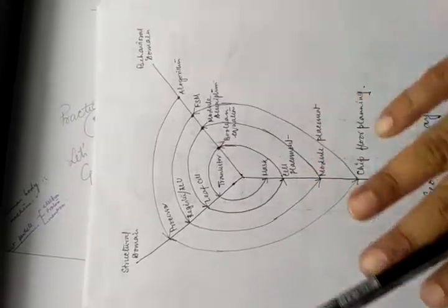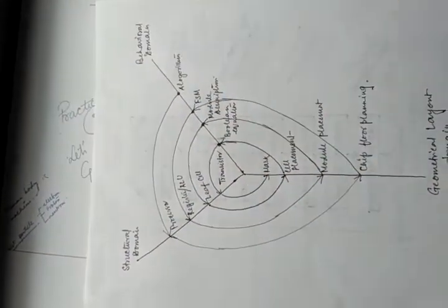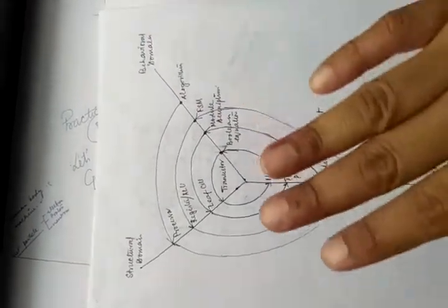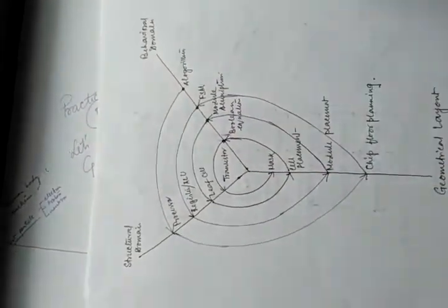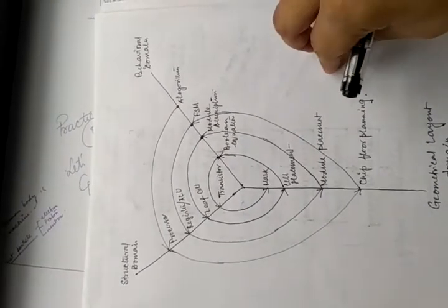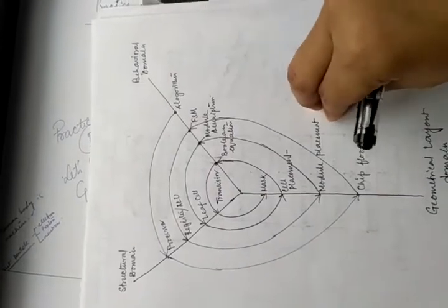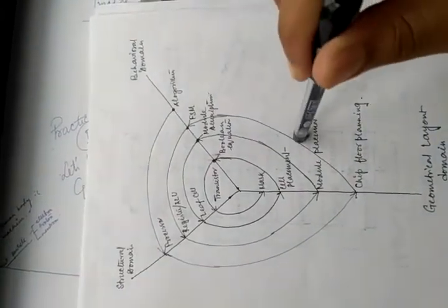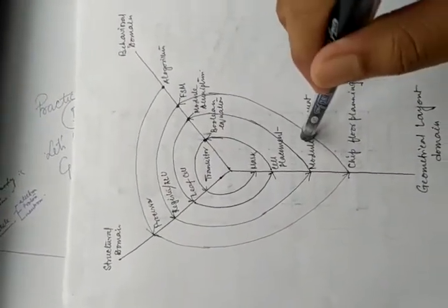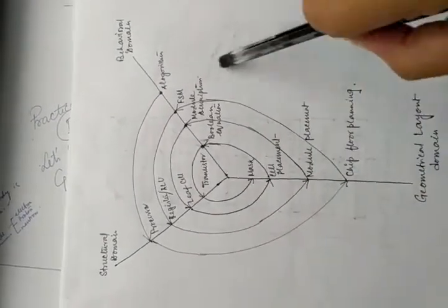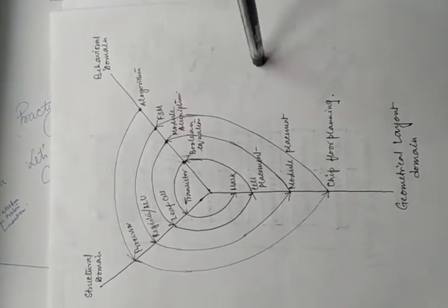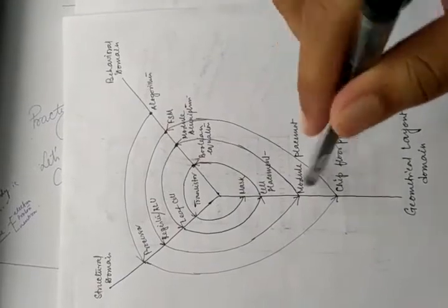Cell placement means, we all know the substrate is nothing but a floor. We have a floor in our house, so the substrate will be treated as a floor, and that floor will be divided into some blocks, and in those blocks the modules will be placed. Which module will be placed in which block is all decided in the logical design part. The engineer will decide which module will be placed in which block. So the overall floor of the substrate will be divided into blocks, the modules will be placed in those blocks, and after the modules are placed, they will be interconnected.